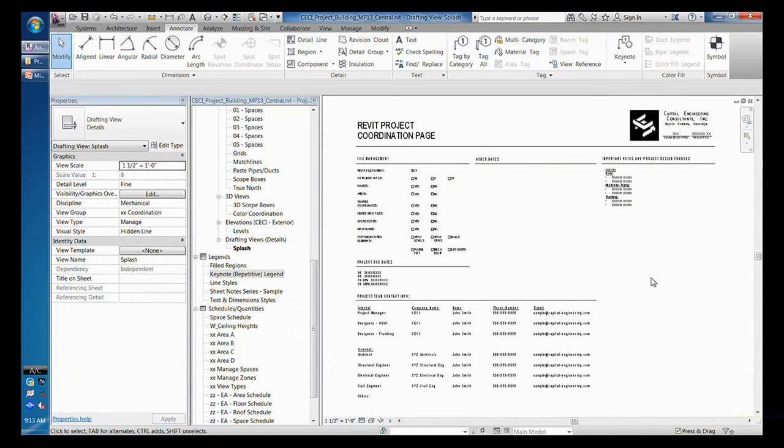It's pretty powerful. It can do all kinds of things. It starts getting into a little bit of programming and conditional statements. But it is extremely powerful, and basically you can get in a project and really quickly see, okay, are my guys using the dimension style that I have set up from my template, or have they created a new one? Or maybe they didn't create it, but they transferred project standards, or maybe they copied the title block, and that carried over all kinds of junk with it.